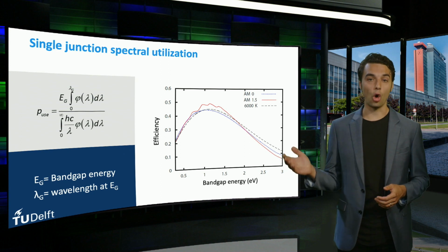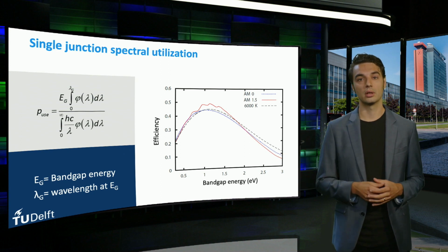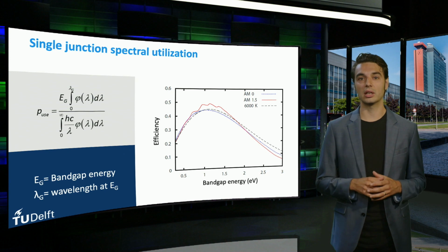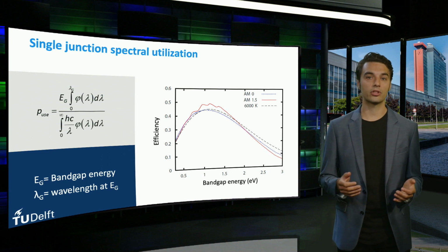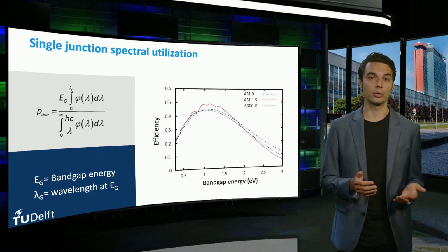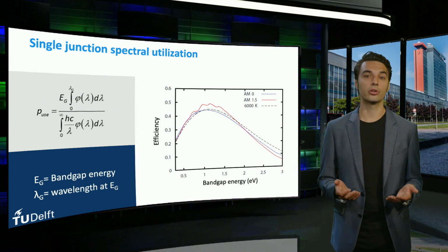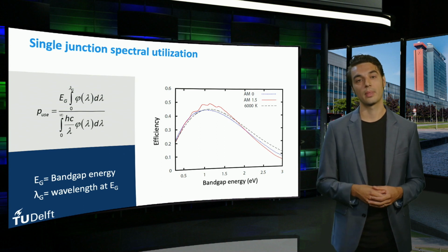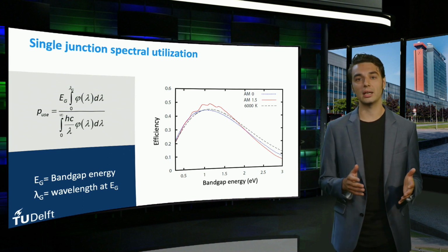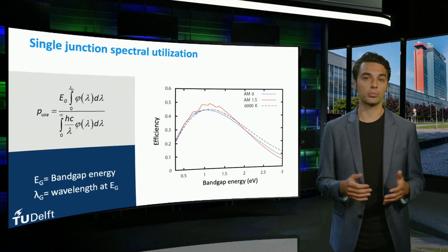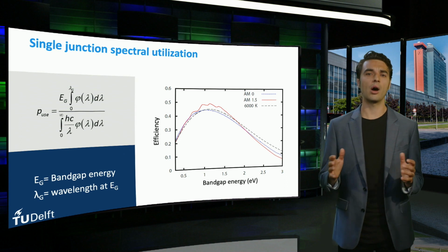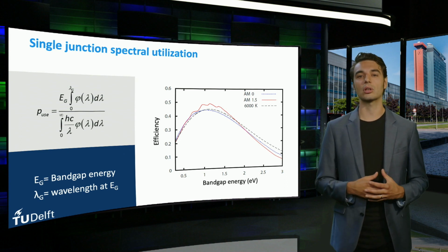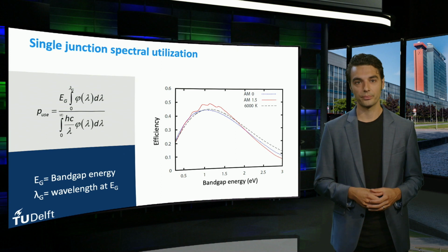As we can see, this optimum is around 1.1 eV. Just another reason why silicon, with its bandgap of 1.12 eV, is of such interest to photovoltaics. Gallium arsenide, having a bandgap of 1.4 electron volts, has a high conversion efficiency potential as well. In the second course, we will show a trick on how to utilize more of the spectrum using so-called multi-junction solar cells. For now, it is good enough just to understand the basic concepts behind spectral mismatch.